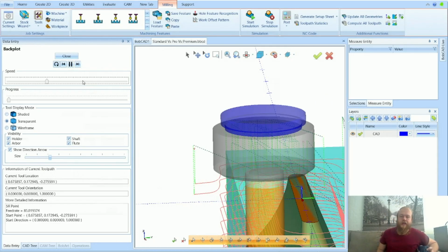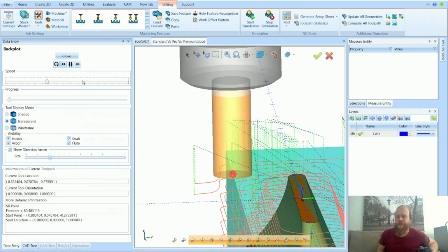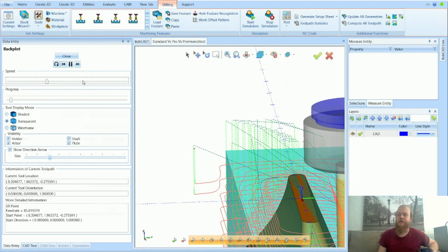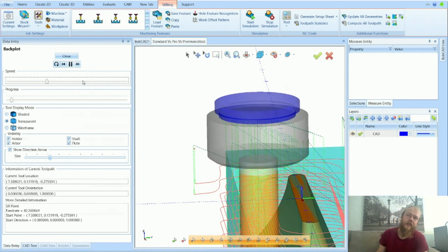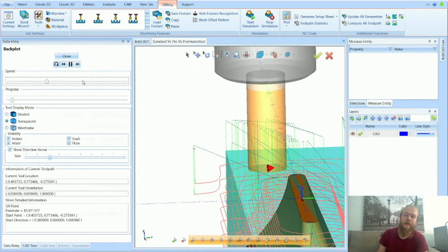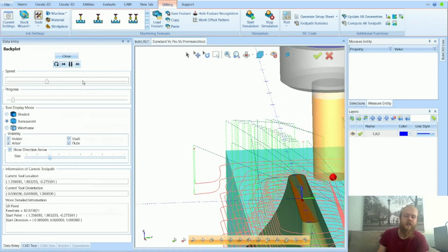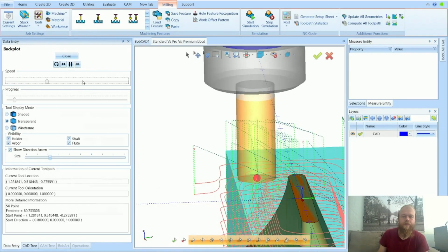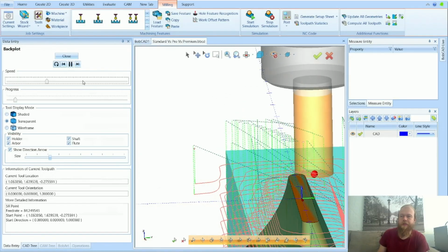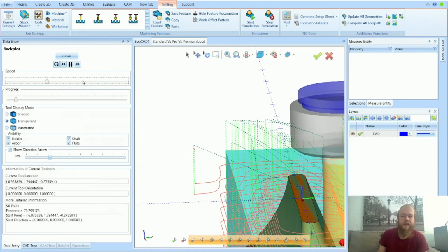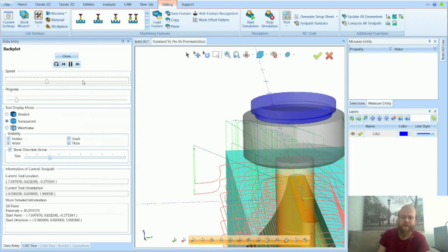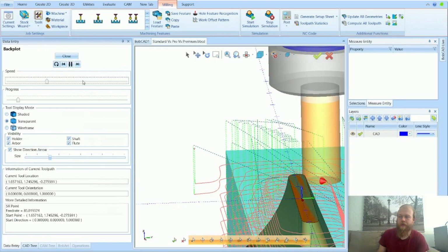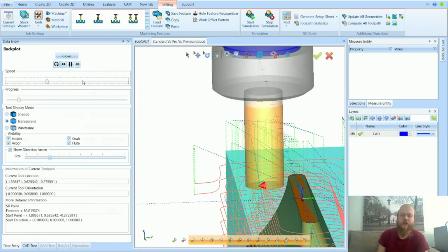All right, so that's the 3-axis standard versus the 3-axis Pro. It offers the side roughing option like this. It offers the trochoidal milling, high-speed machining options. If you guys are familiar with Mastercam, you will be familiar with dynamic machining or dynamic roughing. That's the same kind of operation as our adaptive roughing in the Pro. And we've got some other options like the rest machining option and machine flatlands to finish up the flat areas in our roughing operation so we don't have to come back with a flatlands operation. Let me know if you guys have any questions so far.